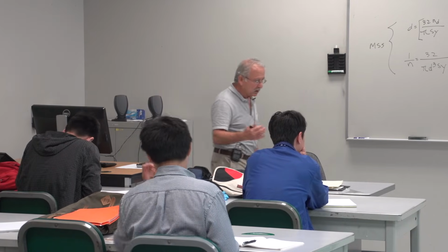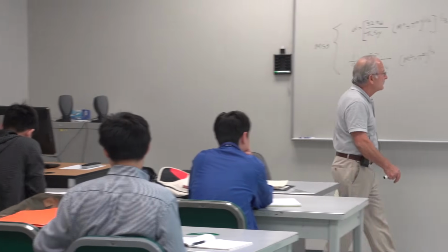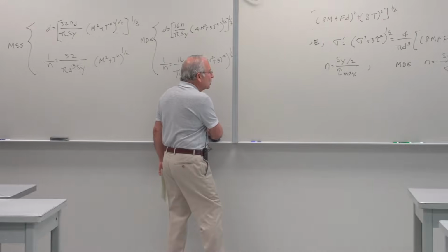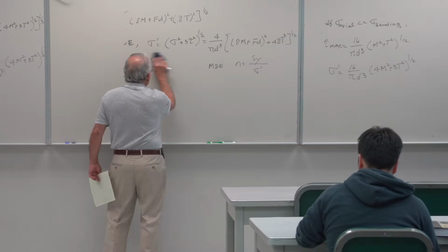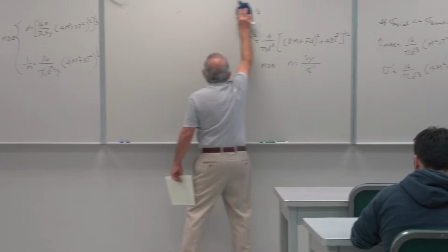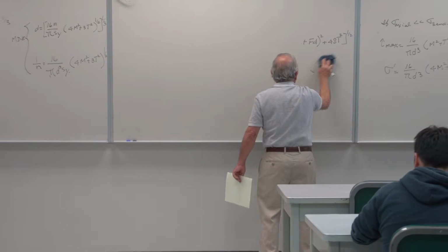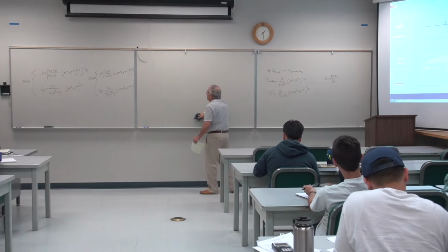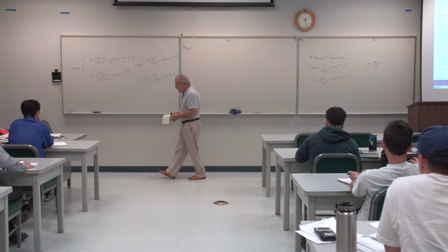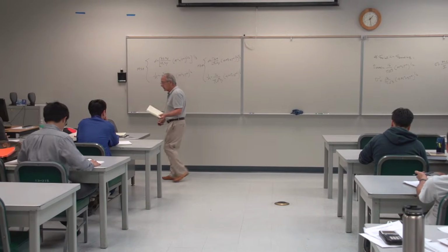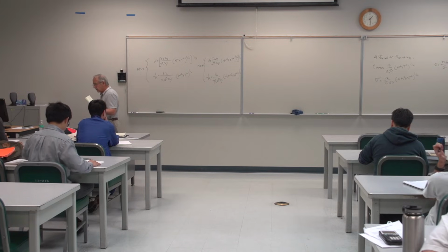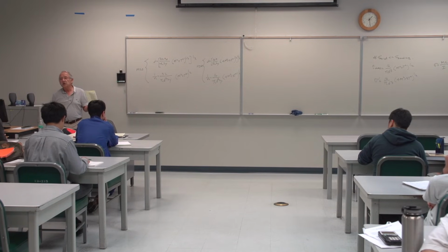We'll look at a general equation. The torque will also fluctuate, so each one will have a mean value and an alternating value. If that's the case, we would like to see how to deal with the failure of the shaft in fatigue.